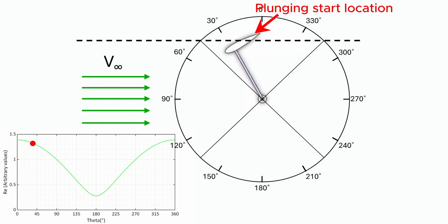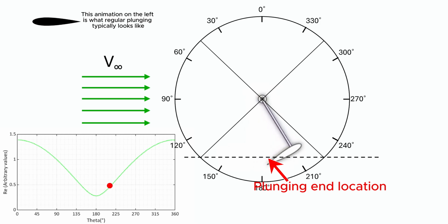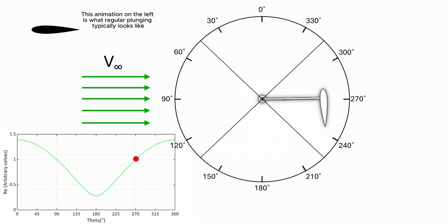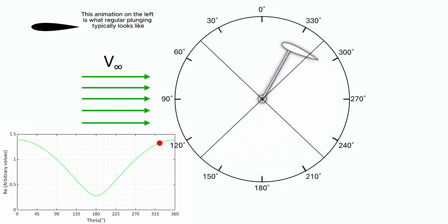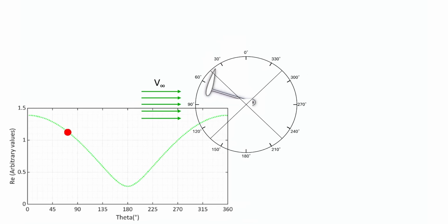The next thing to notice is that at the 0 degrees theta position, the blade begins to plunge downwards with an amplitude equal to the diameter of the rotor. It goes down and goes right back up by the end of the cycle. The plunging amplitude and plunging rate are also huge factors which affect dynamic stall. But you think that's all?